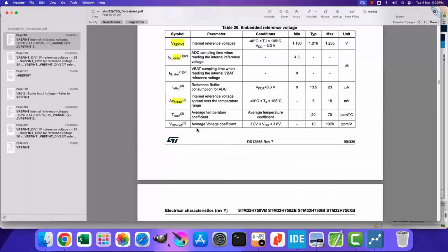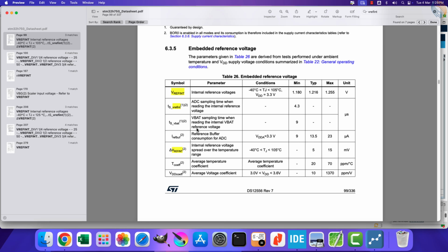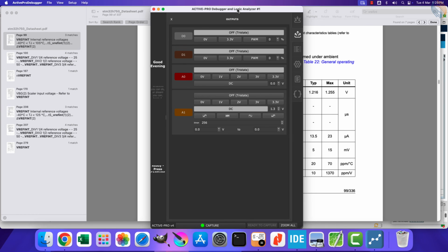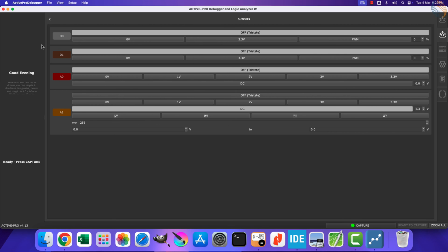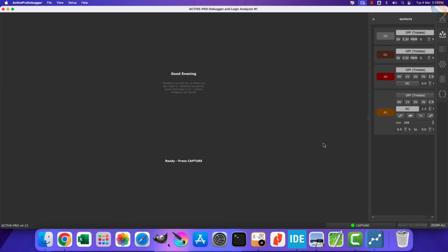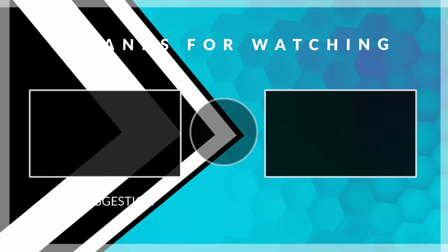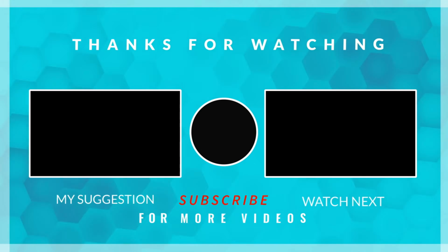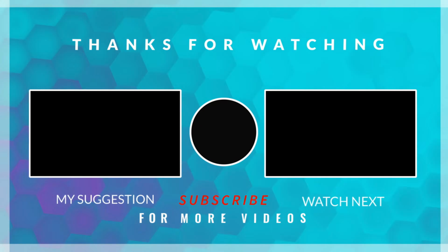So you saw how we can use the external reference voltage to reduce the reference point for the ADC input voltage. This can help us get the maximum resolution, even at low voltages. Also for the devices where a separate VREF pin is not available, we can reduce the VDD itself. So I hope you understood the reference voltages used in the ADC peripheral of STM32.